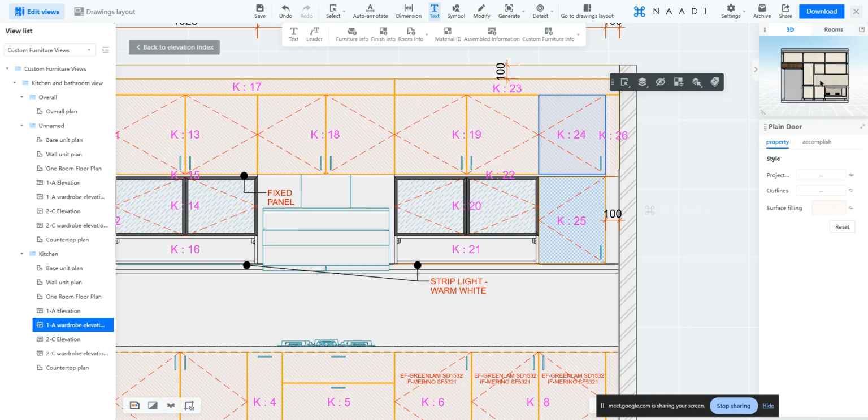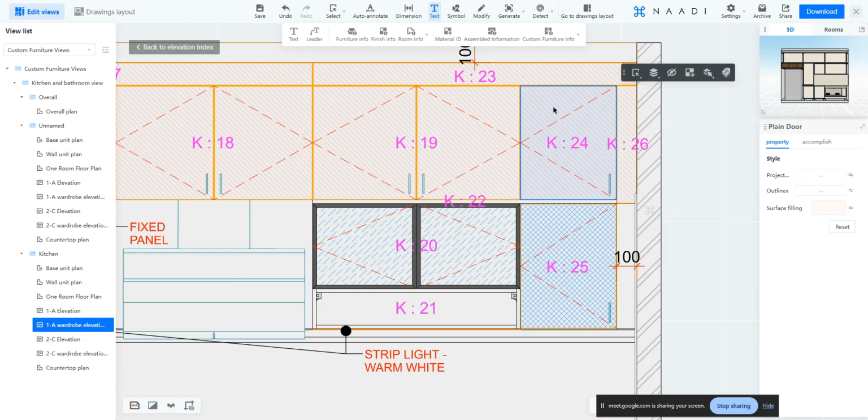If you want to delete it, go to the model, delete that shutter by select by paths, come back here, and it will be updated. But in your 2D window, you can't delete any component. But you can hide it. Yes, let's just say that I want to hide this so that I can see the internals of it in this external elevation itself.